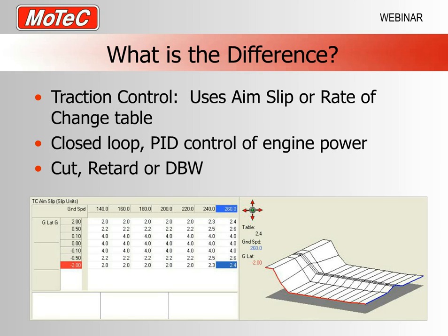I would have something like a 9-position switch, as I mentioned before, and I'd have a few different settings for whether it's a wet track or a dry track. But overall, we give the ECU an idea of what slip we want. It does the control based on what it's actually seeing at the time.